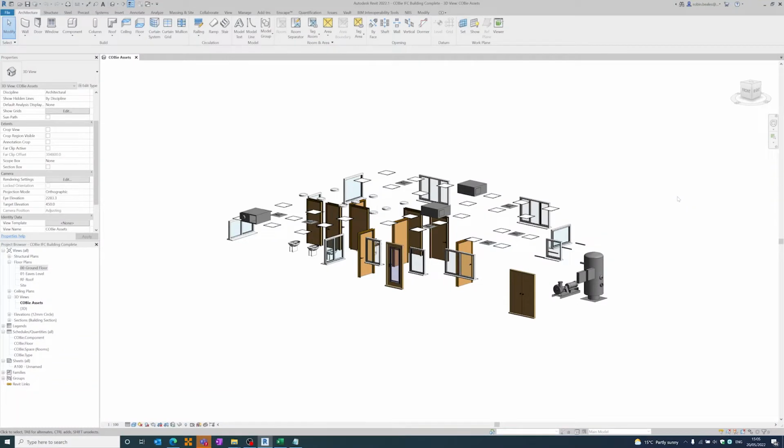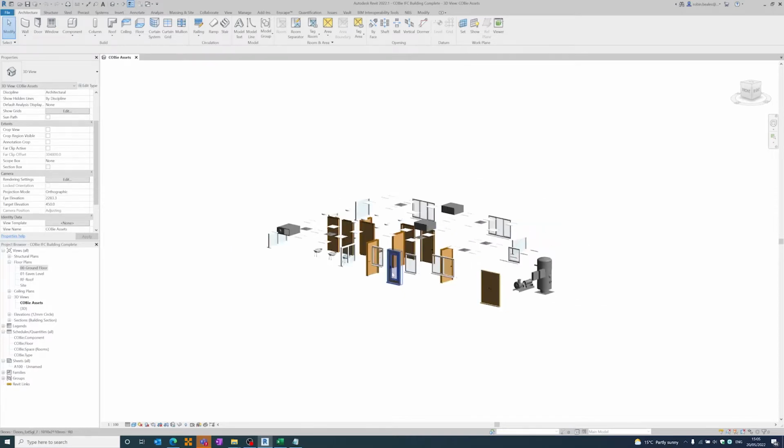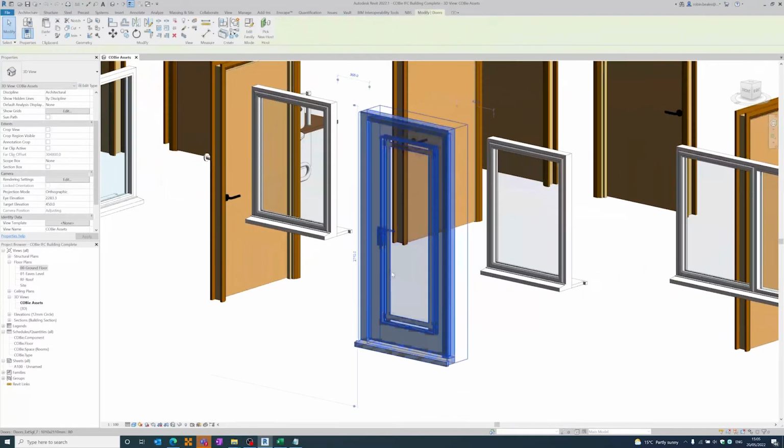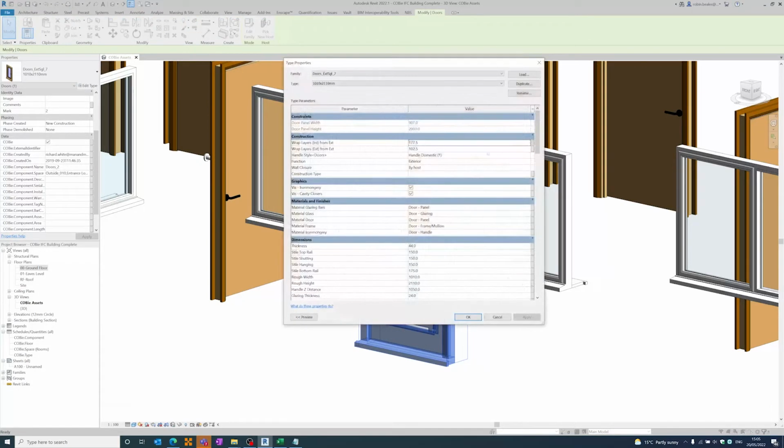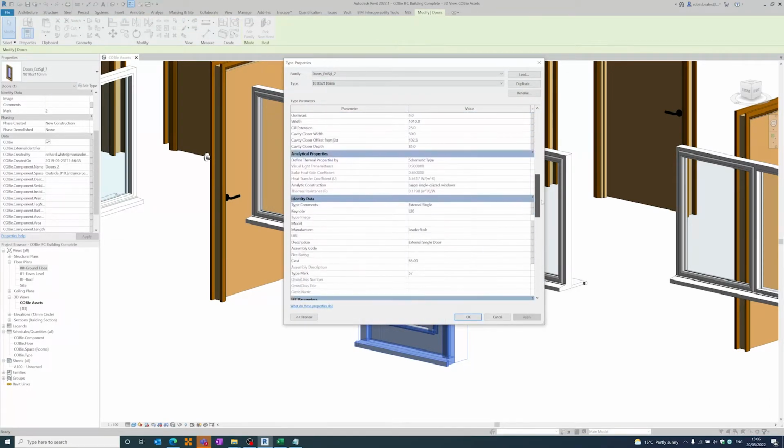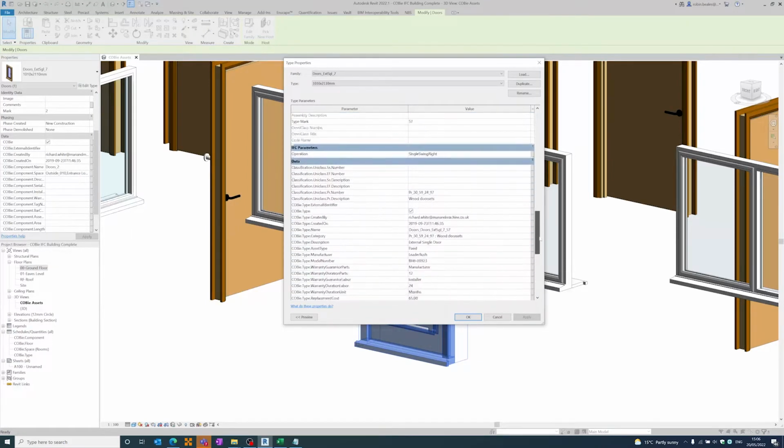Inside of Revit, using the Industry Foundation Class file, or IFC file, is crucial to drive open collaboration and open BIM. The IFC file by buildingSMART International is used as an open, collaborative file format that isn't tied to any individual vendor. The IFC file will export 3D geometry, such as this door, as well as information attached to that door, whether it's instance properties, very specific BIM data like COBie, type properties, or other BIM data like IFC specific property sets or classification systems.